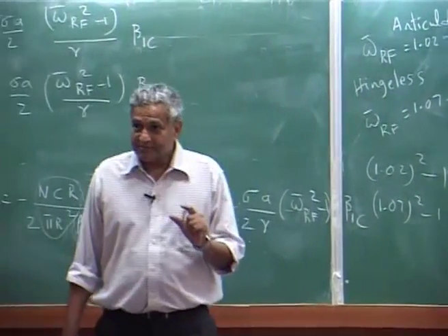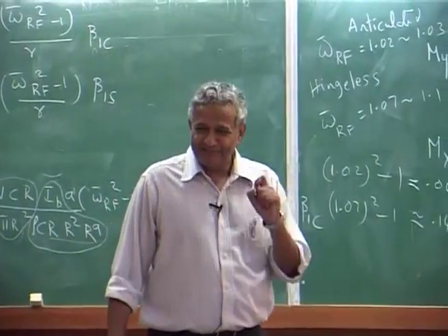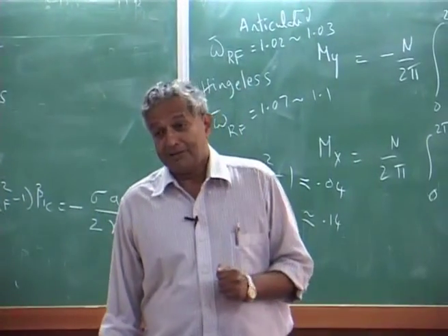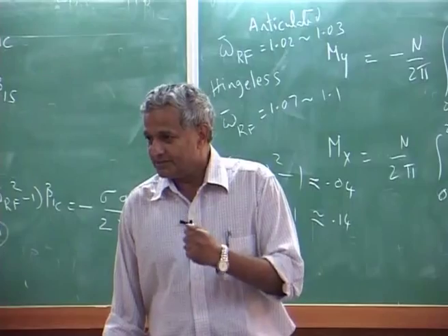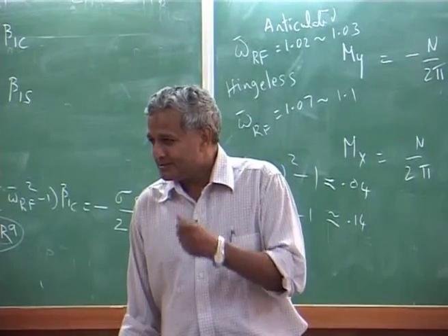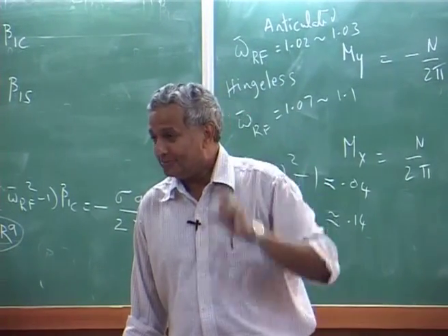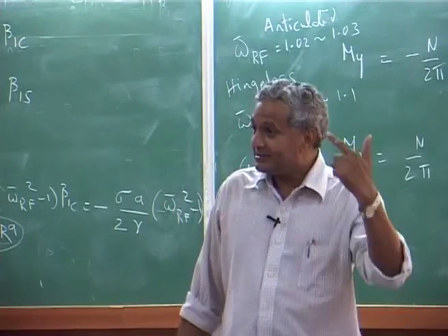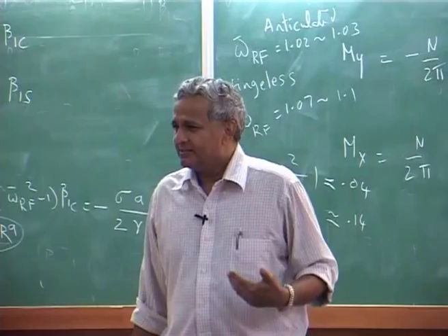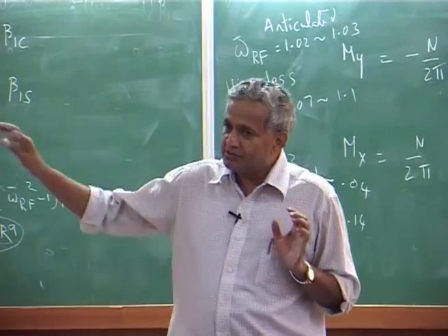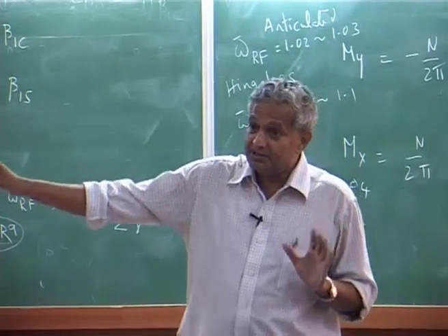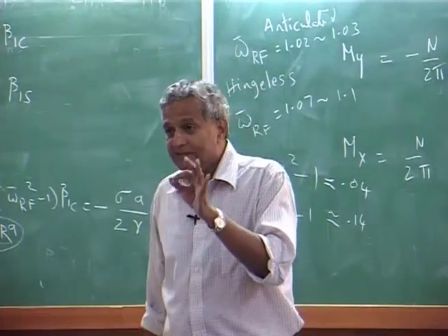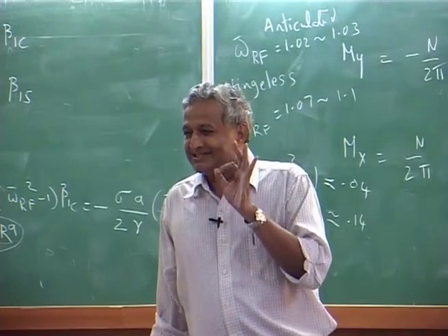Because you find flap frequency is a very, very dominant parameter, really influencing. So, industry spends enormous time in designing and going through the iterative process, several designs. Now, imagine you are actually making a composite blade with a hub design, you must know the flap frequency to the third decimal.